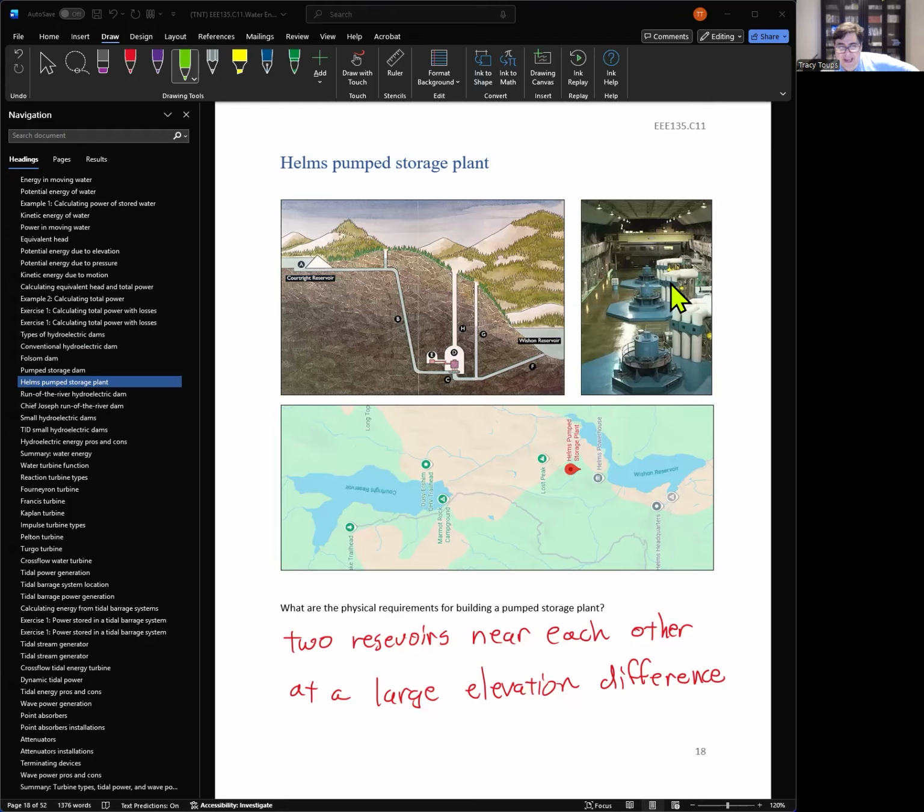These are the 3 cables from the generator out to the main power grid. It's going to be ABC, ABC, ABC phase. And then this goes to the main switch yard with a GSU, a generator step-up transformer, and that goes to the main power grid. But this is typically what the 3 generators look like, and then well below it is the actual turbine.